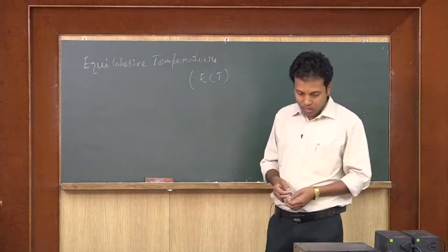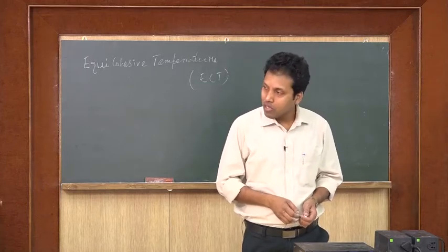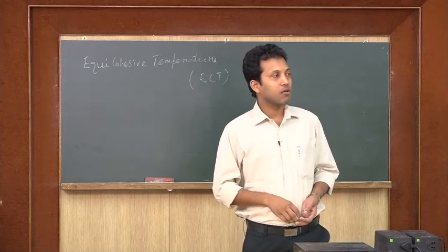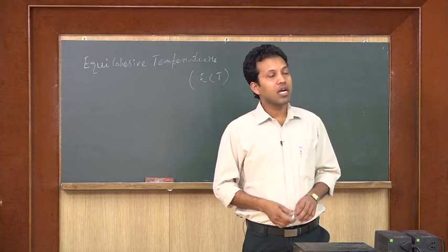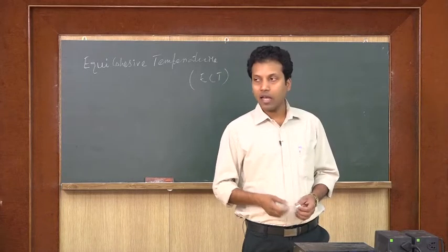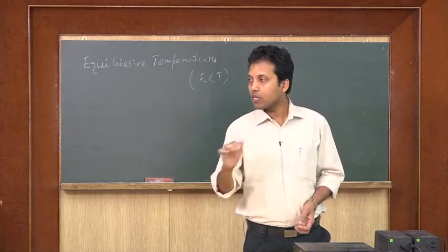So, what we see is the intergranular type of failure. Why? Because at that temperature level we are working at high temperature, so I will have a weaker grain boundary. If you have a weak grain boundary, then a crack which is produced can grow through the grain boundary itself.